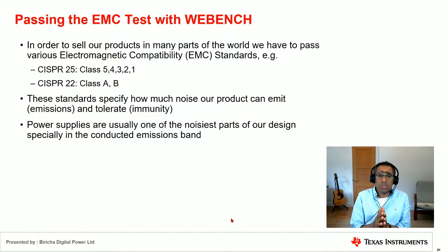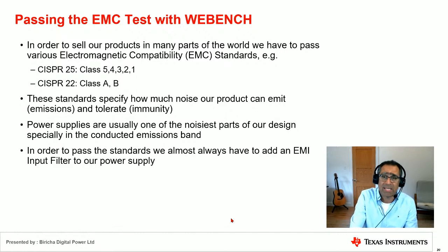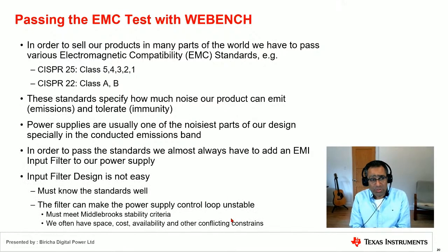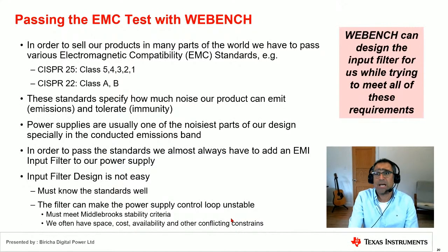Power supplies are usually the noisiest bit of the design, in particular around the conducted emissions band, and therefore we almost always have to add an EMI filter. And of course, it's a very difficult thing to do. You must know the standards very well. The addition of the filter can actually make the power supply unstable, and that's the Middlebrook stability criteria and so on. And WEBENCH now designs the EMC filter for us and therefore can save us a lot of time.